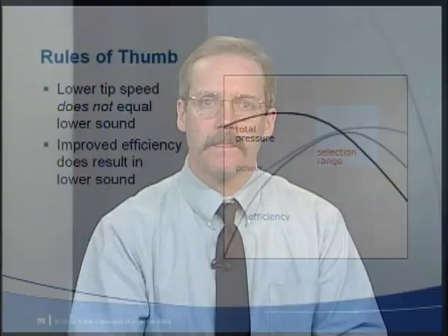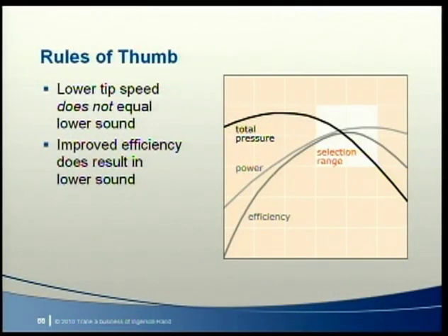Well, remember that the selection program provides unit sound. The acoustical impact of the system must be considered to determine which fan will be the quietest in the occupied space. As a result, octave-band data provides the most accurate indication of equipment-generated sound and should be used to identify the quietest selection. The best general guidance to follow when using a selection program to find a quiet fan is to explore all fan and unit options.